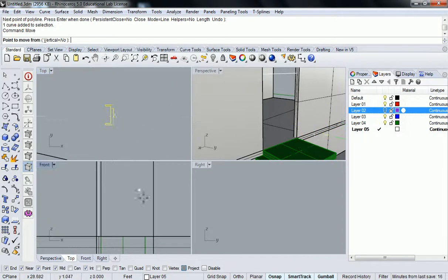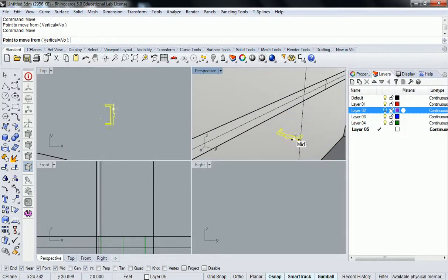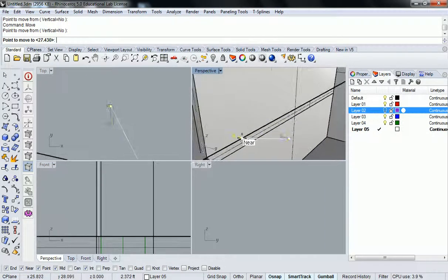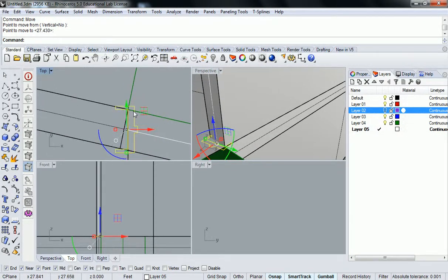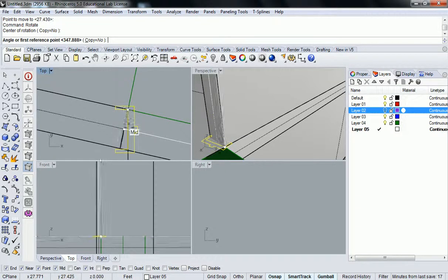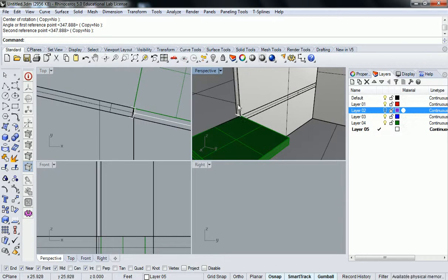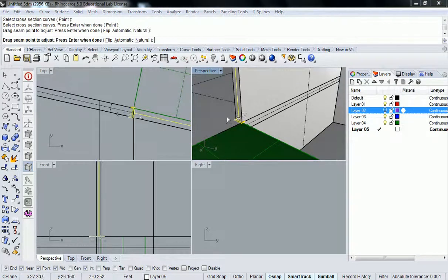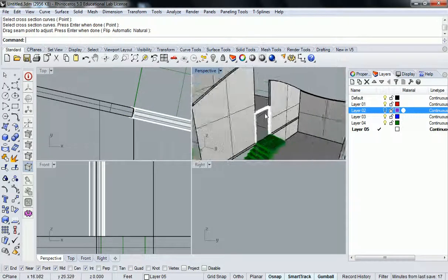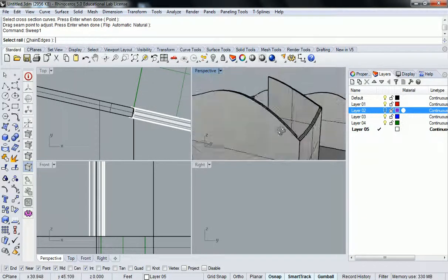So now I'm going to move this. Actually, I'm going to move that with 3D on. Move from here to there. And then I can rotate it. There, now it's in place. I can do sweep 1, select that. Oh, whoops, I keep thinking it's another step. That, enter, enter, enter. Okay, so now you've got a very detailed door frame, which is actually kind of more